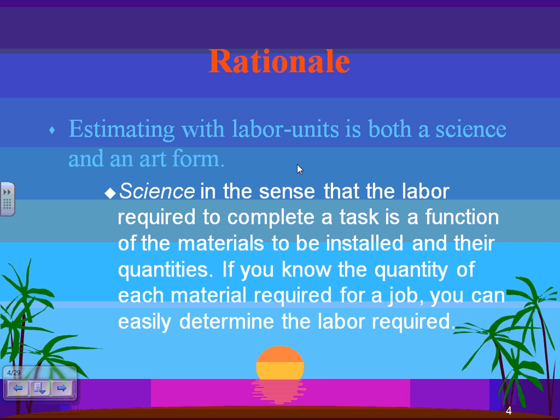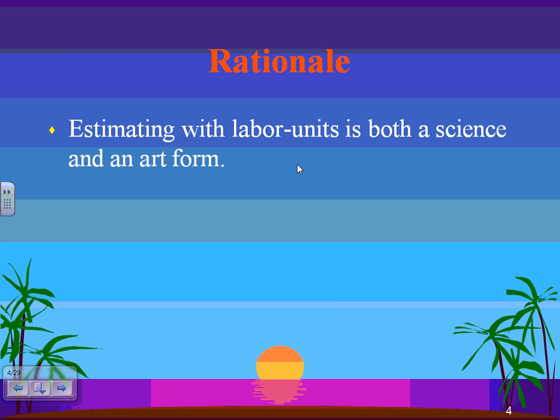Okay, so I'm going to go ahead with this rationale, and I think I agree with it. Estimating, guys, is a science as well as an art. Why science? Because it doesn't take a smart person to count all these fixtures and assign 0.5 of an hour for each one of them, right? This is where the science is. We assign a labor unit in hours to a fixture. So all I have to do now is count all my fixtures, assign a labor unit in hours for them, and you're done. Isn't that science? Count, assign.